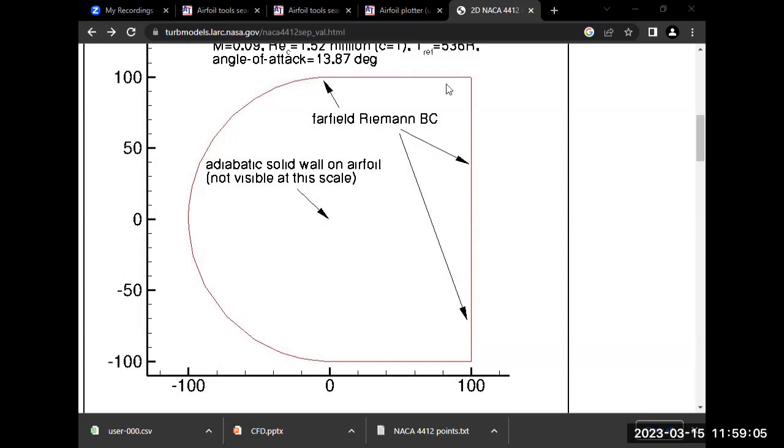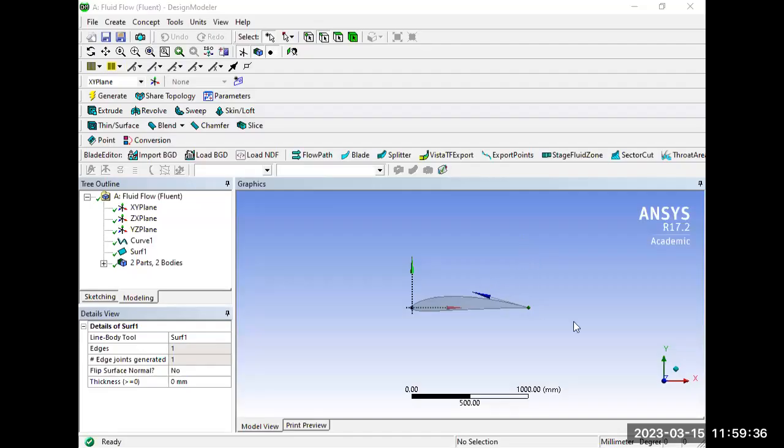So similarly, I will make this kind of domain outside the airfoil, and then I will simply subtract that airfoil from this fluid domain. We will then simulate this fluid domain after the subtraction of that particular airfoil. So first, my main motto is that I have to make this fluid domain outside the airfoil. So we are going for the C kind of mesh.